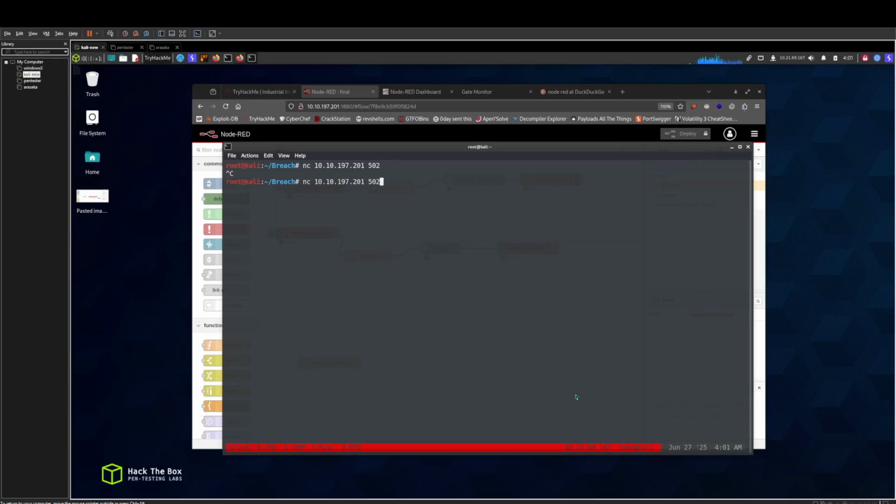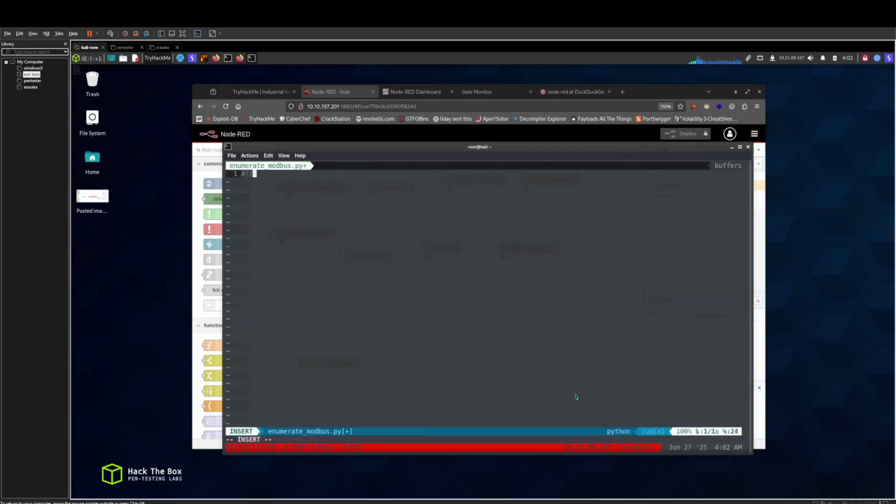So how we can interact is using a library in Python called pymodbus. So what we can do is, let's go into Vim and create modbus.py, and we can do the usr/bin/env python3 shebang line, and we can import pymodbus.client. Sorry, we can import. Oh, did I forget how to use them? From pymodbus.client import ModbusTcpClient. I guess that was it.